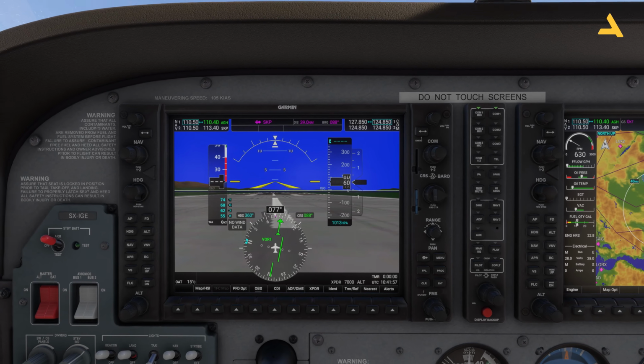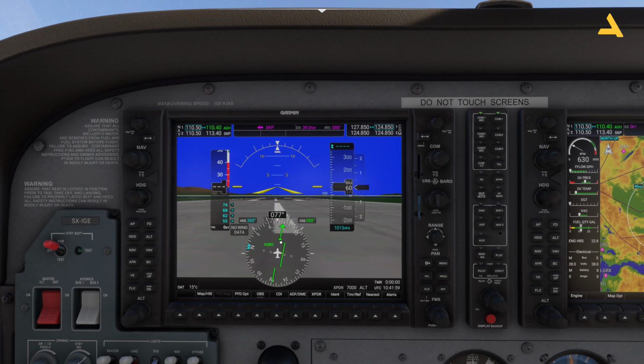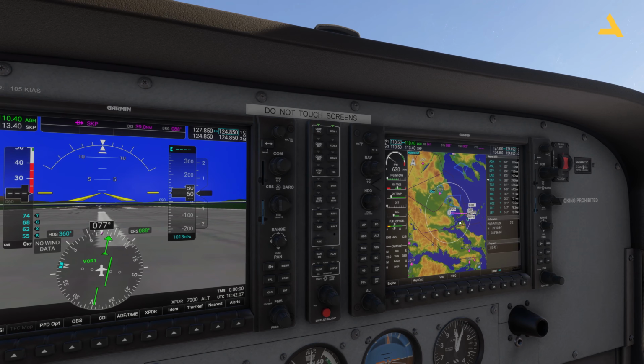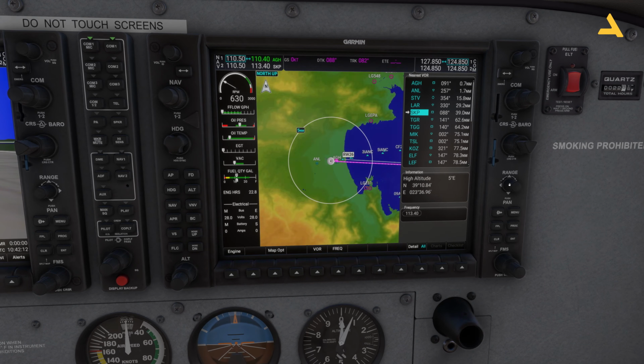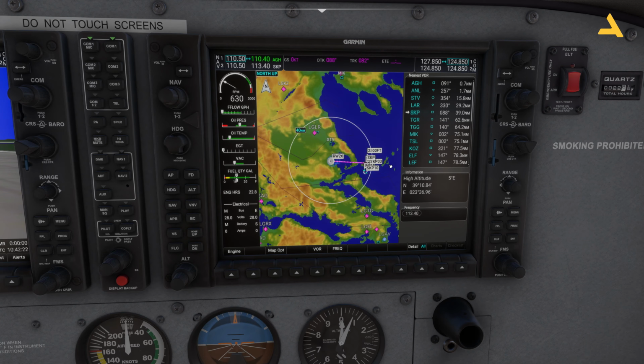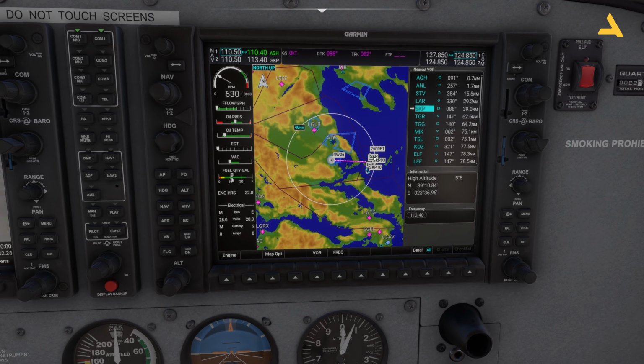That's it. Now this is the course deflection indicator, which is telling you where your course should be, and either you're following that line or not. When I'm talking about the line, if you look at this map, this is actually the magenta line. As I was explaining before, if you have to travel in 88 degrees, you can just travel to 88 degrees from anywhere, from here to here or anywhere in the world. But obviously it will not take you to this point. So you have to track this outbound radial for SKP, 88 degrees.